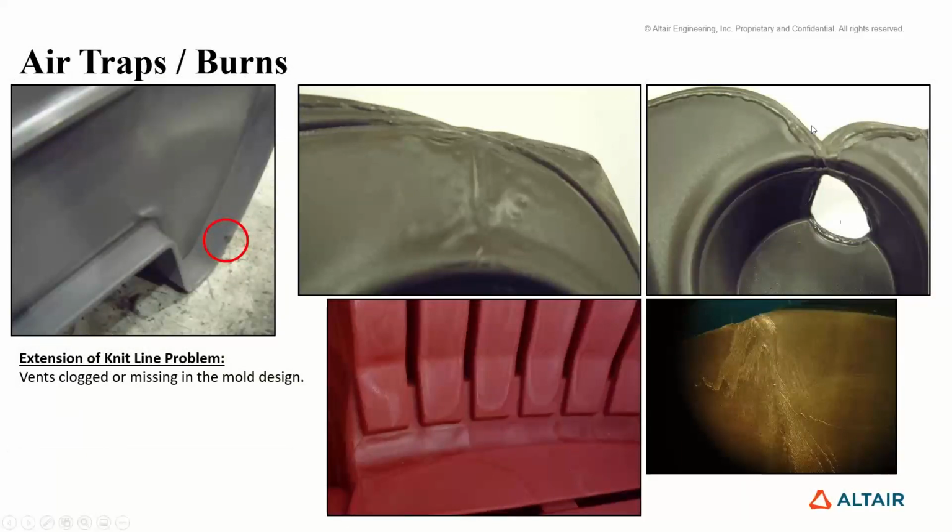So when you see something like this out here, and there's our part again, here's that air trap that was causing these wrinkles as this thing blasted through. And later on, here it is in the final product. As we got a good look at it with the right lighting, you can really see the wrinkles in that surface because of that air blasting through there. They're huge. It's just a big problem. And this is a console part for a car. This is something you're going to see.